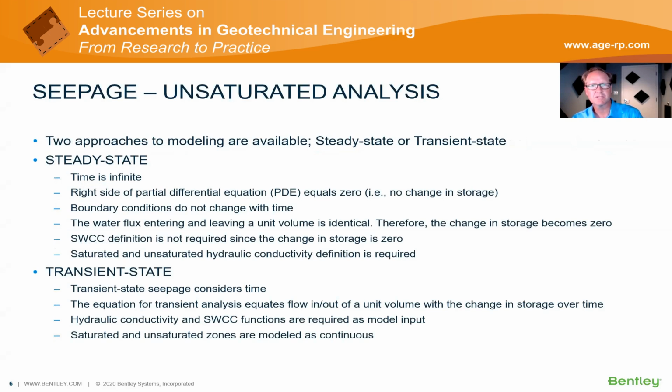Let's talk first about seepage modeling, unsaturated analysis. Just as a refresher, we have really 2 approaches. We can do steady state modeling or transient state numerical modeling. In steady state, time is infinite. The right side of the partial differential equation that was shown earlier has our storage term, and it's equal to 0 in the steady state condition. Boundary conditions don't change with time, and water entering or leaving the model is identical. Therefore, the change in storage becomes 0, and the SWCC definition is not required since the change in storage is 0.